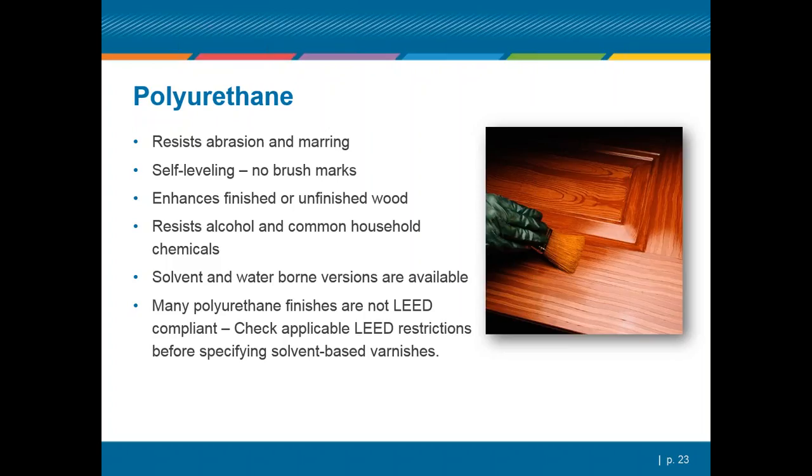And there again, that's a big component because we really don't know what these surfaces are going to be cleaned with once they're put into service. And so if we can have something that's pretty forgiving across the board, then that's a nice thing to have. There are solvent-borne versions and waterborne versions available. And many of these polyurethane finishes are not LEED compliant, and then we need to check with applicable LEED restrictions before specifying solvent-based varnishes or polyurethanes. And again, we'll talk about that in a little more detail in our last slide before we get into the non-proprietary part of our presentation today.